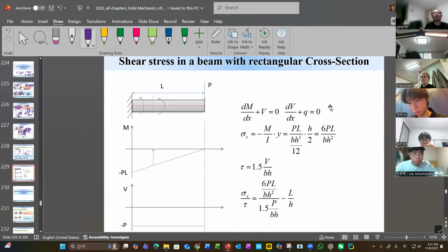Okay, well, let's try to compare the stress-wise. See how much stress, let's say, for example, we have a P here, we have a moment here. The maximum moment, I mean the variation will be like this, right? 0 at the top, and the maximum here is simply because the moment here is PL.